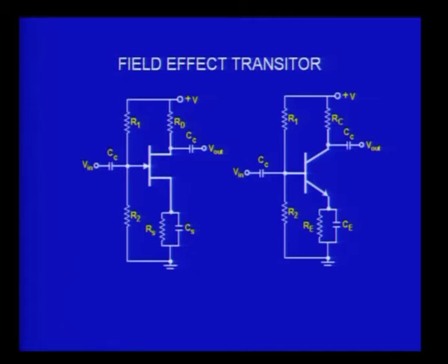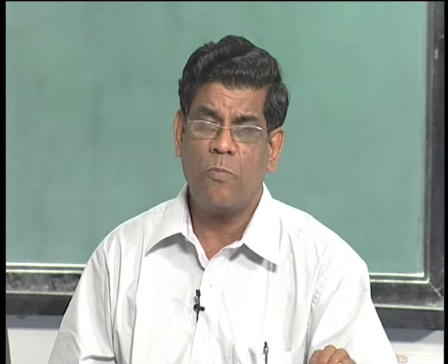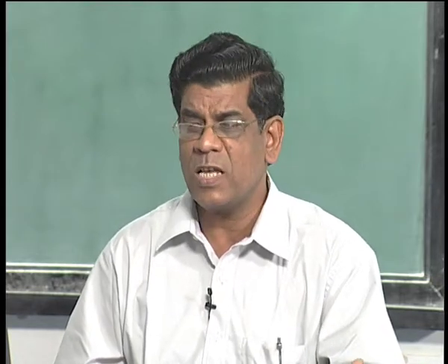If you have a triode circuit, all that you do is take out the triode, reduce all the voltages, remove the filament supply, and put in a field effect transistor; effectively, it should in principle work. It is not as simple as that, but in most cases you would find it reasonably good to try a design like that.